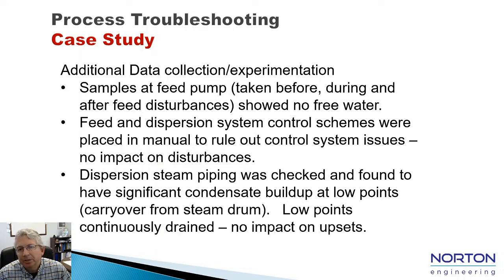Feed and dispersion system control schemes were also placed in manual to make sure that there were no issues with the control system malfunctioning and causing these variations in flow and pressure. There was no impact from putting those control valves on manual on the disturbances.